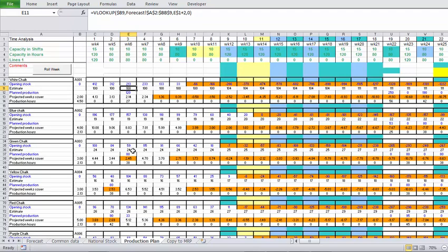Last step from there, so big power of this spreadsheet is it gives you your view going forward. So this is what's typically called your master production schedule. It gives you your capacity requirement going forward 52 weeks, allows you to plan for your workers. It allows you to plan for your machine capacities. If you get, like we saw earlier, up to that 21 shifts, you have to run that continuously. You're going to have a look at buying more equipment.